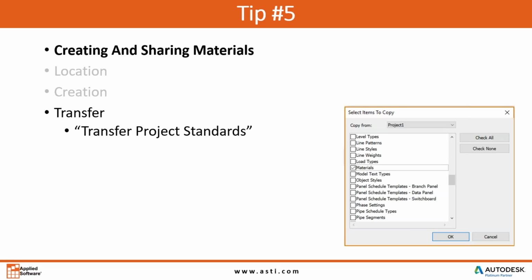It sends that to a specific project. You have to have your other project open, the one that has the material in it, and then your new one you're going to. That's a little side note caveat, but that's a way we can create a material, do some custom editing, and share it out. Again, good, quick little tips.